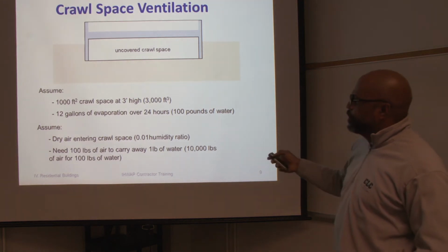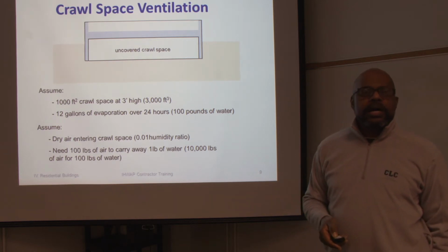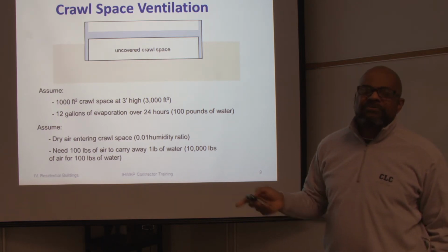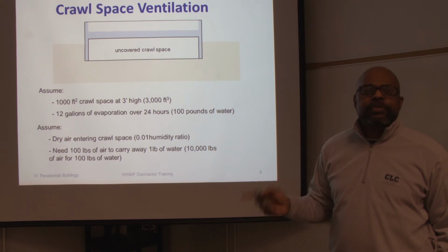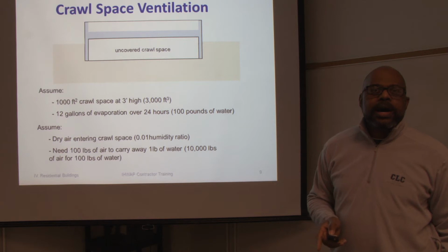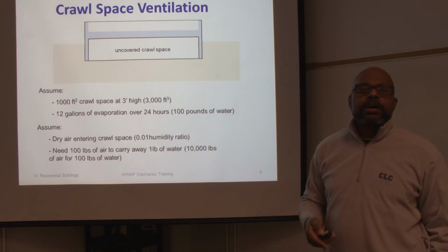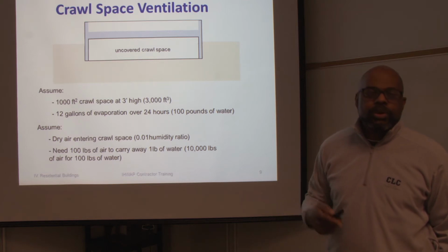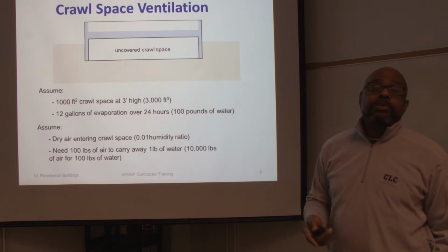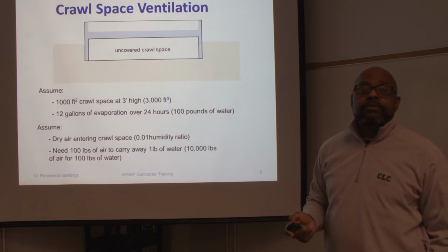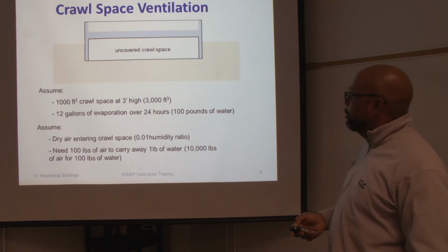Ventilation, we're not going to go into this too often, but there has to be a certain amount of airflow in a crawl space. Unfortunately, the vents we put in would never be large enough to get enough ventilation through a crawl space to keep moisture from leaving it if you get moisture in it. So a lot of times you say if you seal the walls up as well as possible, you really don't need any ventilation if we seal the walls from moisture or vapor.